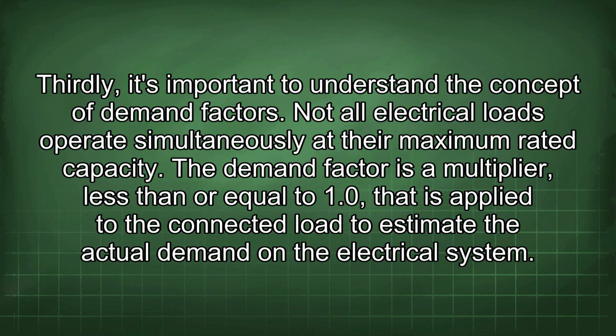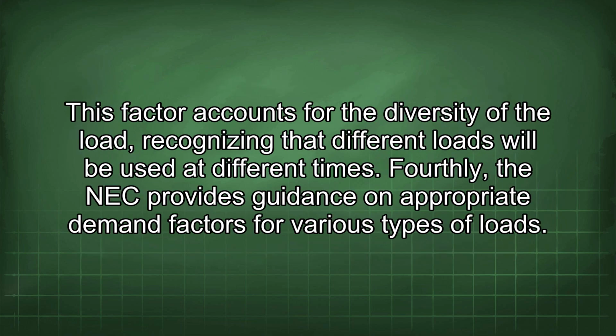Thirdly, it's important to understand the concept of demand factors. Not all electrical loads operate simultaneously at their maximum rated capacity. The demand factor is a multiplier less than or equal to 1.0 that is applied to the connected load to estimate the actual demand on the electrical system. This factor accounts for the diversity of the load, recognizing that different loads will be used at different times.